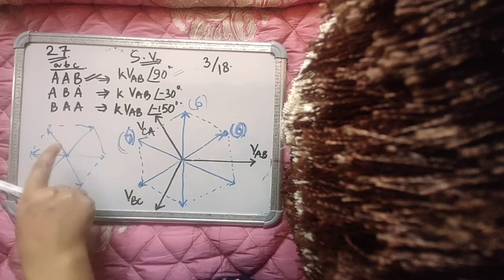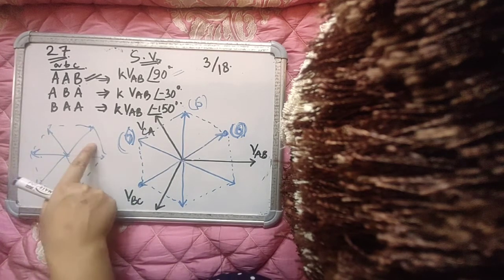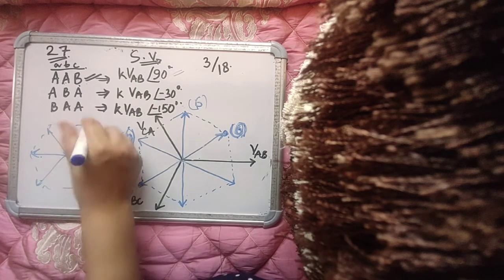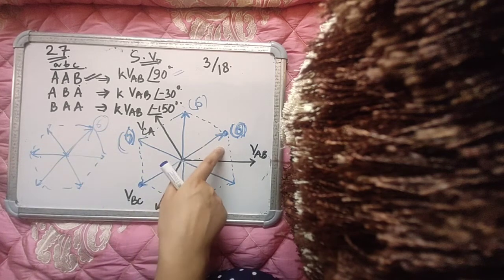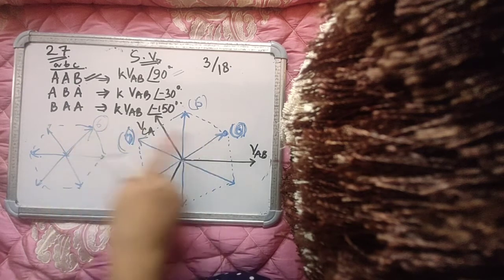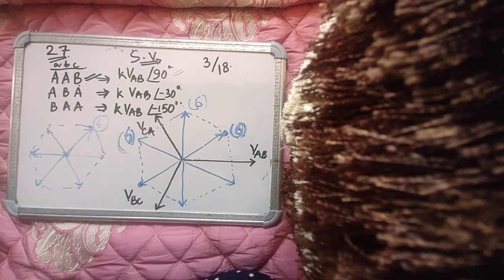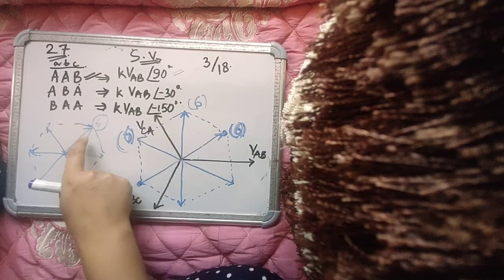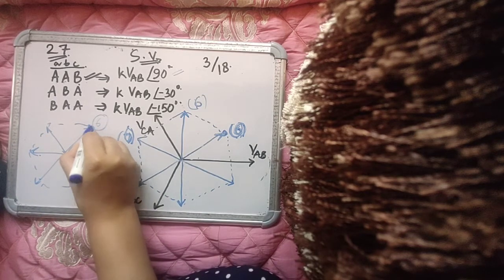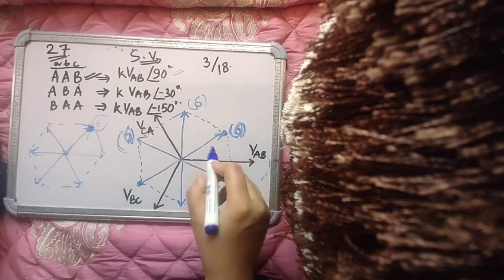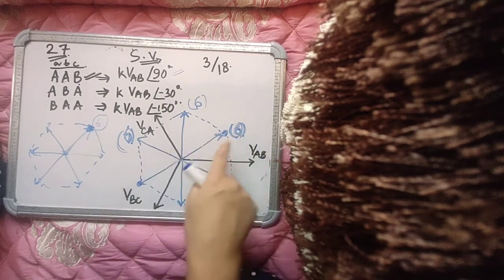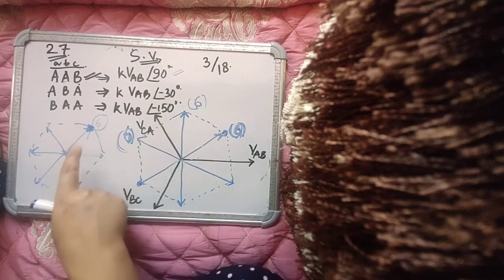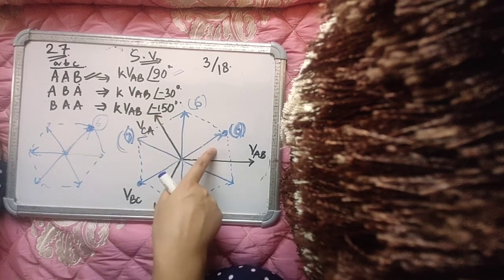And then whatever source current is desired, a sinusoidal source current, you will check which sector it is lying in. There will be 6 states contributing to this vector, and you want a particular voltage in this sector. You will combine the two pieces of information. You will see which state, there are multiple states giving you this position on the current space vector diagram, and then there are multiple switching states giving you the position you want in the space vector diagram of the voltage, because you are simultaneously controlling the source currents and the load voltages.